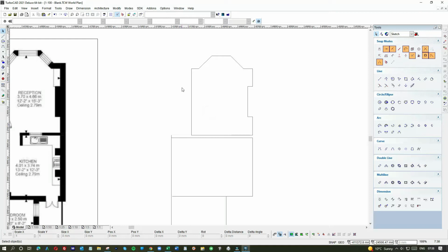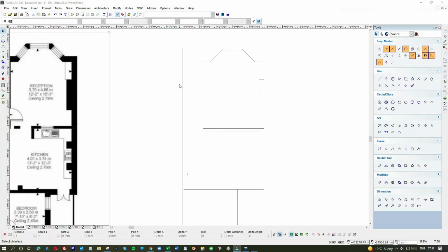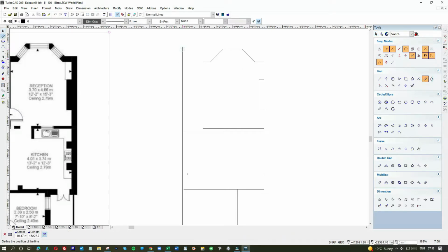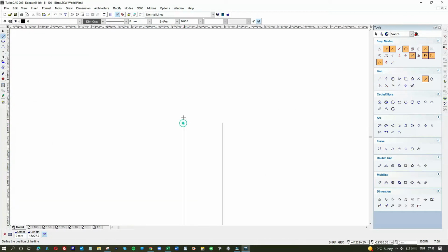Now, this is a communal hallway, and this would be what we consider to be the party wall. When it comes to party walls, general thickness is 2 bricks wide and a big chunk of plaster on either side. We allow, the general allowance, 285. So tab minus 285. There we go. And let me get to half of that. Simple way of doing it.